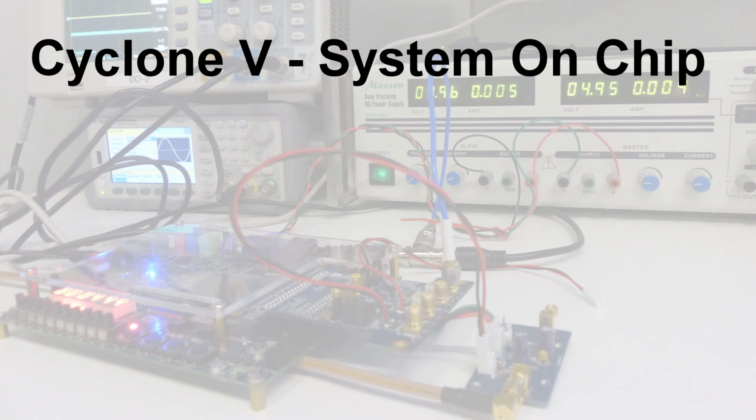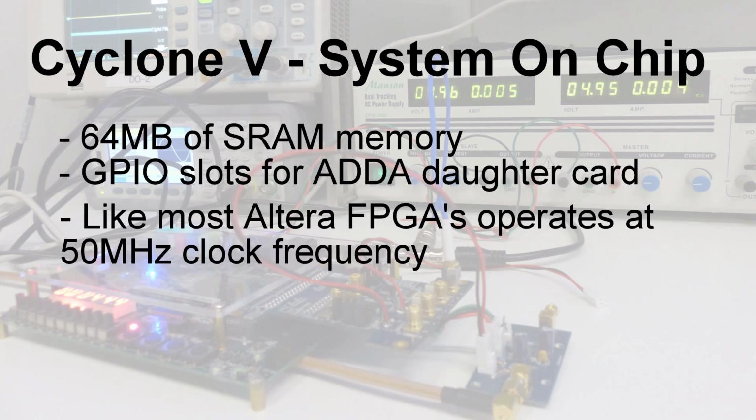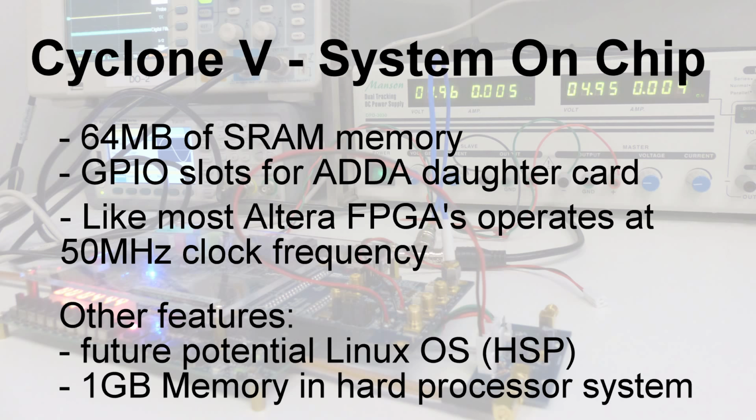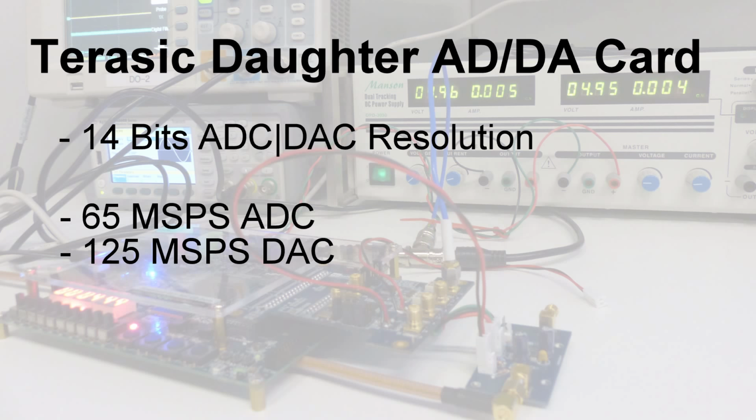It has a fair amount of memory, which is quite useful for things like filters and filter design, which have to store coefficients. In addition to this, our FPGA operates at a 50 megahertz clock rate, which is ample for being able to sample a 3 megahertz carrier wave. The Terasic daughter card itself has 14 bits of resolution, and so satisfies our 12-bit resolution requirement. It also clocks up to about 65 megahertz sampling rate and about 100 megahertz output rate.